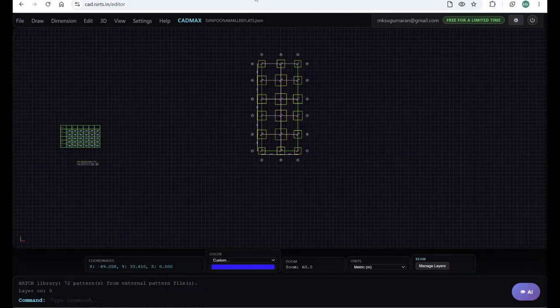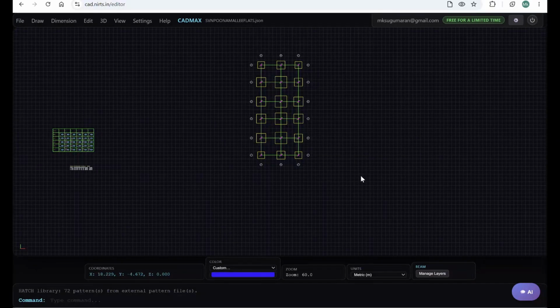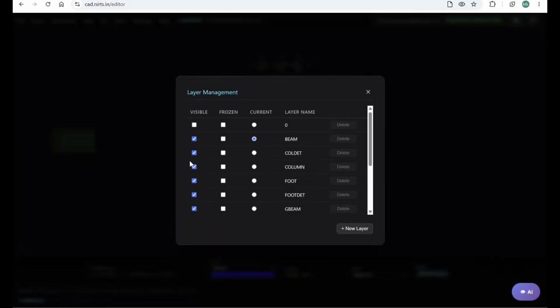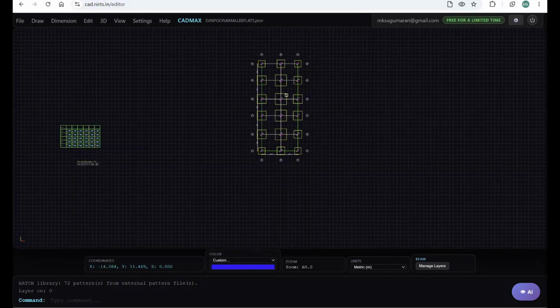For this I open the drawing we have already designed and detailed in the previous example. I will make all the layers of structural elements such as columns, footings, grade beams, slabs, ground walls, floor walls, parapet walls and joint layer created during analysis and design visible. The detailed drawings of beams are not necessary. Now you are seeing the structural model with all layers on.